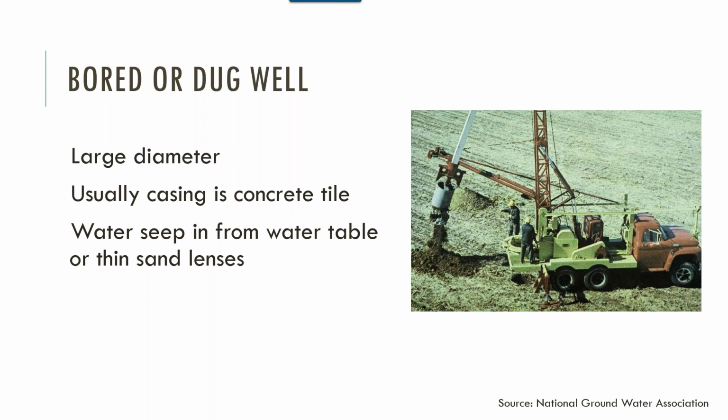I'm assuming you're familiar with cisterns, which you used to collect runoff from your roof. The same type of thing. You store it for when you need it. We have a well owner who contacted us from the western slope of the Rockies, whose well is in granite, and it only pumps a half a gallon a minute. So in his case, he pumps that well basically all the time at a half gallon a minute, and then pumps it into a cistern that he put in the ground there so that he can pump from the cistern to his house to have water supply, because that's the most amount of water he's going to get.